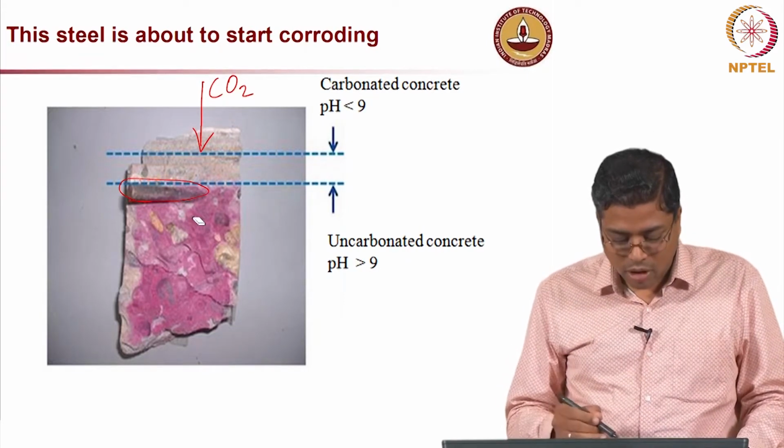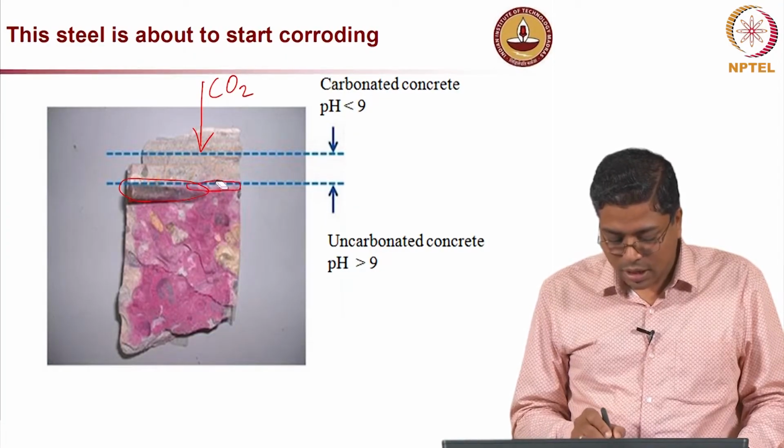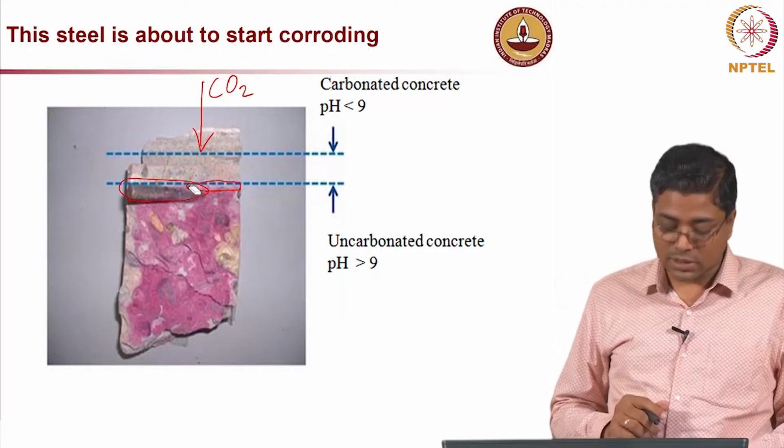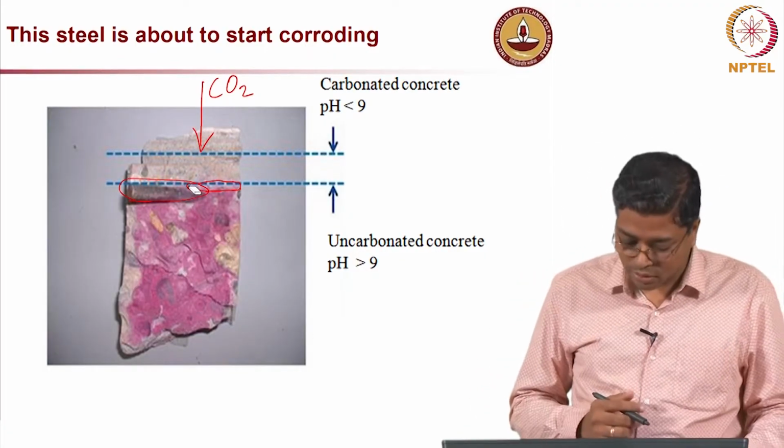Now, if you wait for a longer time, you will see that this region also becomes colorless, and that means the steel gets exposed to carbonated concrete and the pH is low. So, it will start corroding.